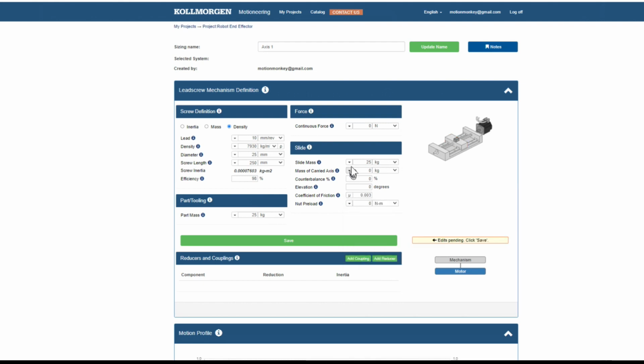The down arrows on the left show unit conversion numbers that can be selected, while the units down arrow on the right lets you switch units. Note that changing the units does not change the number entered. After the data has been entered for the mechanism, it must be saved by either clicking on Save or by hitting Enter.